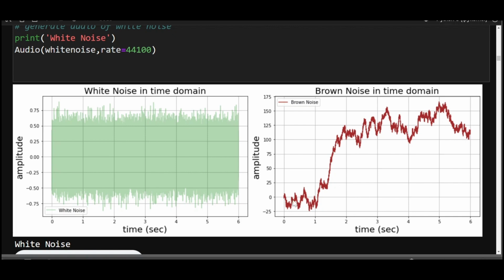But when we see this signal, it starts off from 0, and if we draw a mean line, it will go somewhere like this, which means that the mean of this signal itself is changing, and that's the classic definition of a non-stationary statistical noise. Not only is its mean changing, the variance or the standard deviation of this signal is also changing. So here we have some variance, some fluctuation, and here we just have a straight line, no fluctuations, which means the standard deviation has gone to 0. It's just the mean which is shifting now. And then we have the mean becoming almost constant here, and then some standard deviation happening. And thereafter again, the signal mean is rising up. So that's how a non-stationary signal looks.